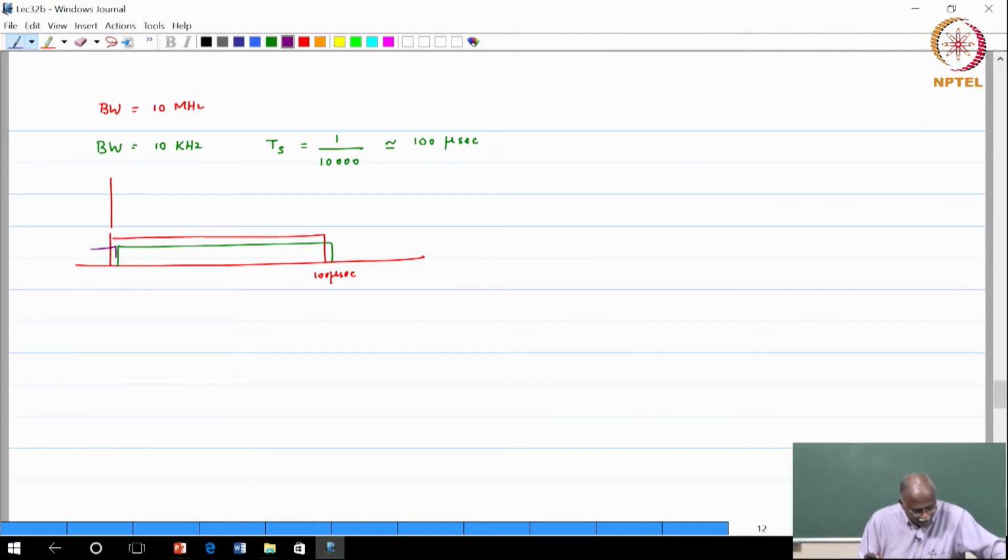As we mentioned yesterday, if your RMS delay spread sigma tau is less than 1/10 of your symbol duration, 0.1 times the symbol duration, then you can consider the channel flat. So this particular scenario would be a flat channel.